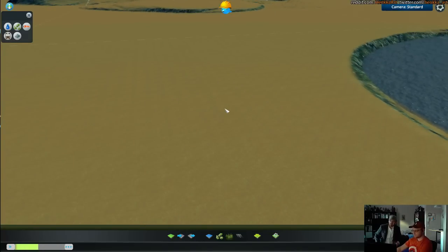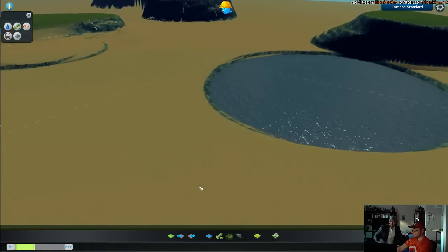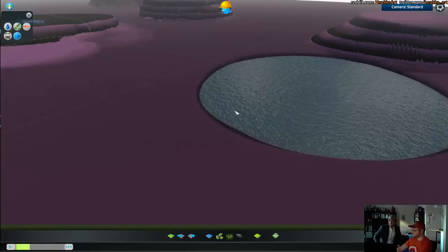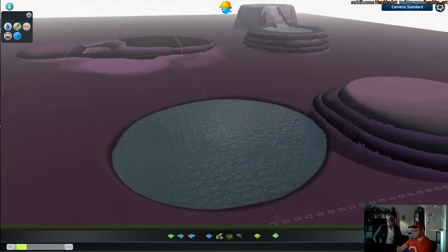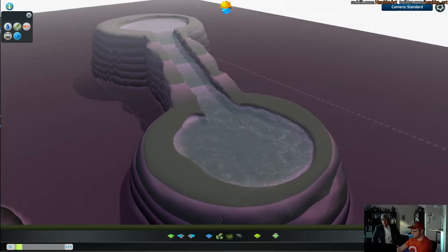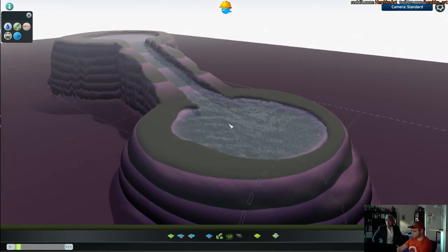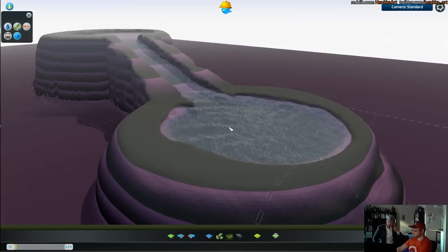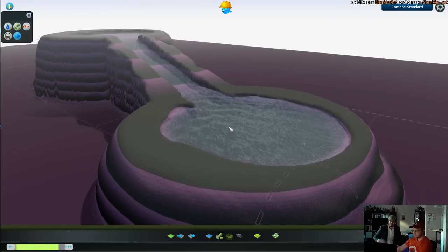And while you're still touching the water, let's show one more view mode, which is relevant for editing water, which would be the terrain heights. So this is essentially showing the different levels of the terrain, so you can guess where the slopes are, because with the perspective camera and the lighting in the editor, sometimes it can be difficult to perceive if some place is higher or lower than another one.